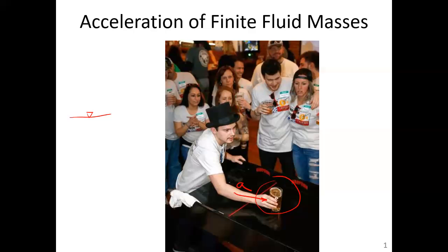And this is the handout for today. We're employing an acceleration field to a finite fluid volume. And when we do that, the laws of fluid statics need to be modified. Why? Because before, under this scenario, the only acceleration was the gravitational field. And under this situation, you have not only gravity, but you have the a_x, an acceleration in the horizontal direction in gravity. So you have this new acceleration field. And that is going to dictate pressures.